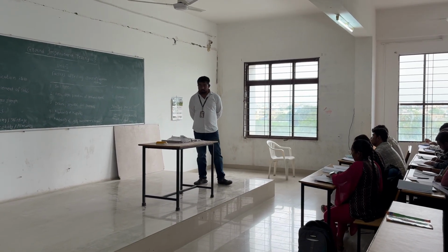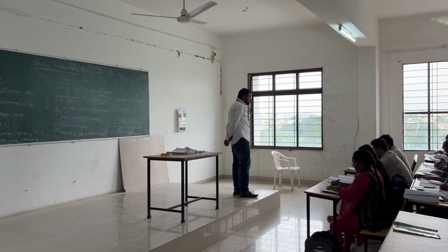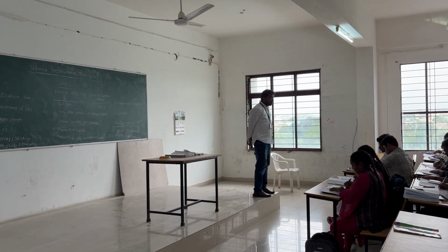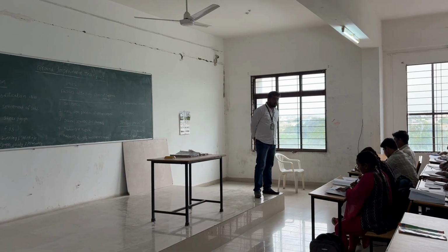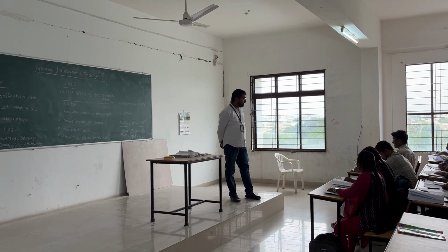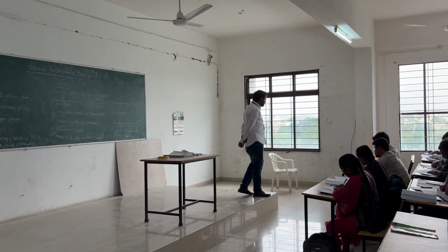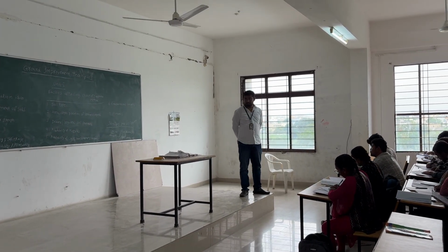For cohesive soil, cohesive soil is known as fine-grained soil, like clay soil and black cotton soil. For that soil, we need to improve the strength of the soil, to reduce the swelling and shrinkage, to reduce permeability. All these maximum properties we need to improve for the fine-grained soil. Why? Because the soil is weak.